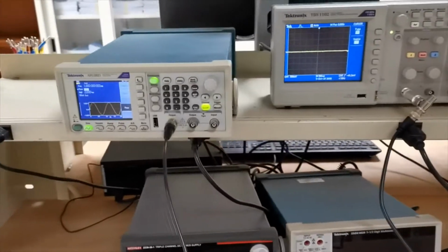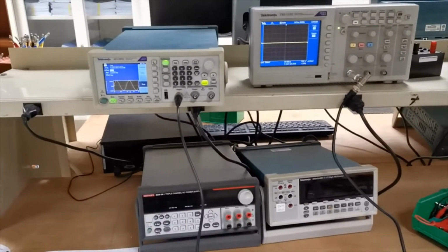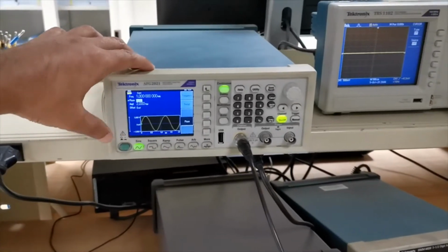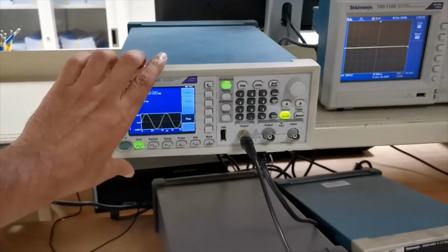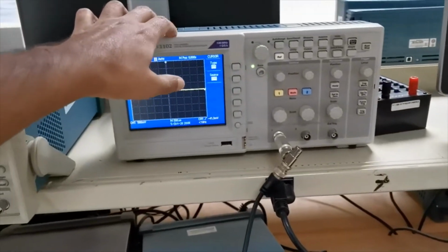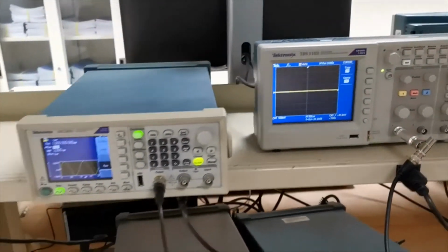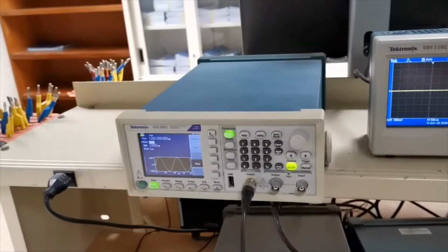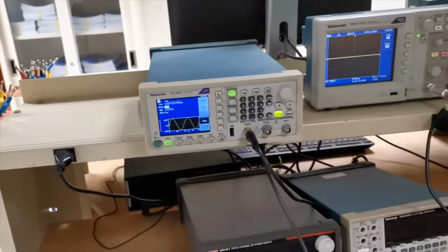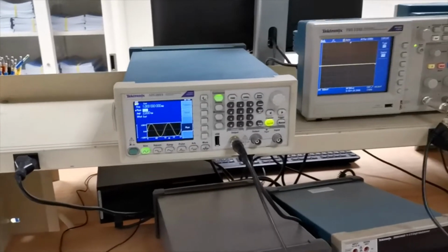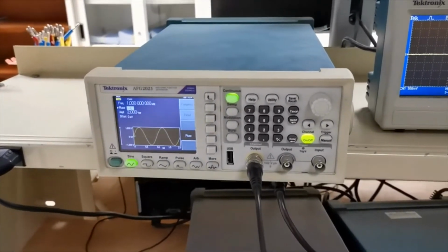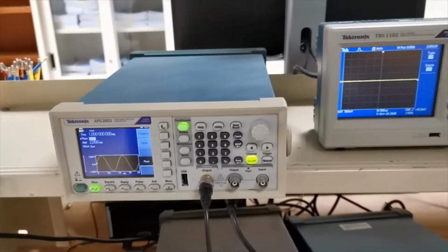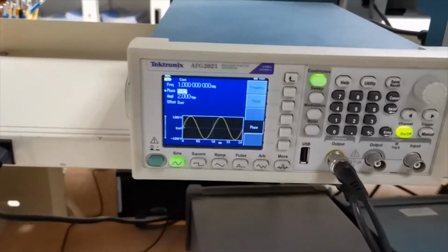Okay. So in the first simple experiment, we'll just have a waveform. We will generate a waveform in this function generator, and we'll just observe this waveform here with certain quantities, like the frequency and time period, which are related to each other, and also we'll see the amplitude, the phase and the offset value. So let's see what we have here.